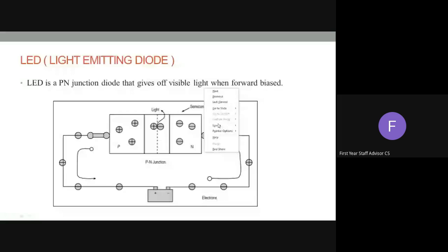Forward biasing means connecting the P side of a PN junction to the positive terminal of a cell or battery, and don't care about which power source here, connect the positive electrode of this power source to the p side of a p-n junction, and the n side of a semiconductor, or n-type material, is connected to the negative terminal of the battery. Such an arrangement or circuit can be called forward biasing. So what happens when we forward bias a semiconductor?